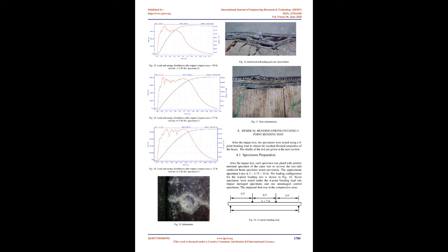3.2 Specimen Preparation and Impact Test. Due to test chamber height limitation of the DynaTup impact test machine, specimens of sizes about 2.36 by 10 inches were cut from the overhanging portion of the full-scale beam tested previously. This portion was not loaded in the previous test and thus was treated as virgin. The beams were cut at the middle depth. As a result, the specimens had only one skin and a core with only half thickness, as schematically shown in Fig. 8. Once the specimens were prepared, they were impact tested.